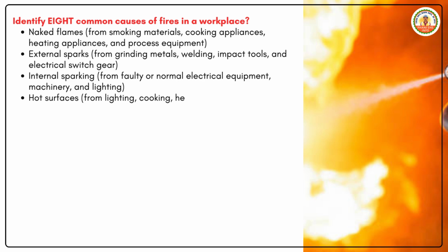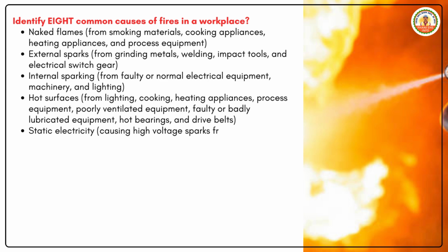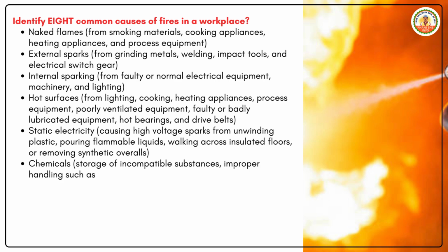Hot surfaces, from lighting, cooking, heating appliances, process equipment, poorly ventilated equipment, faulty or badly lubricated equipment, hot bearings, and drive belts. Static electricity, causing high voltage sparks from unwinding plastic, pouring flammable liquids, walking across insulated floors, or removing synthetic overalls. Chemicals, storage of incompatible substances, improper handling such as recapping containers giving off flammable vapor.